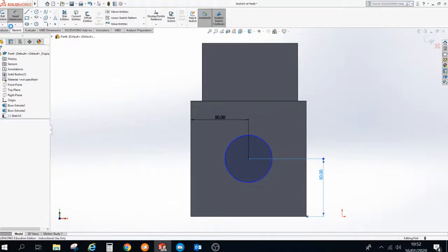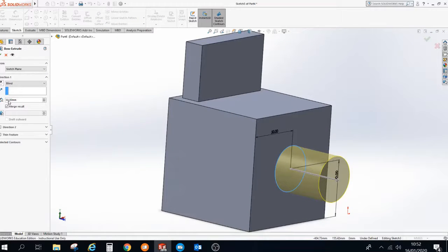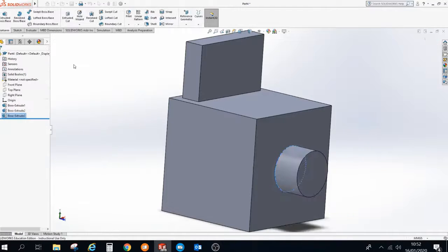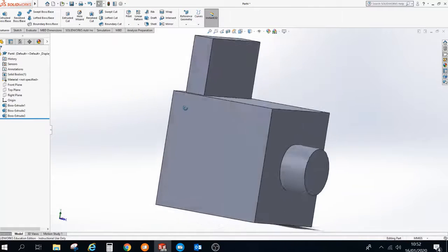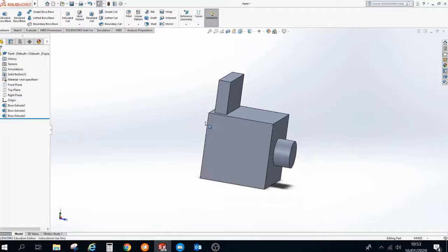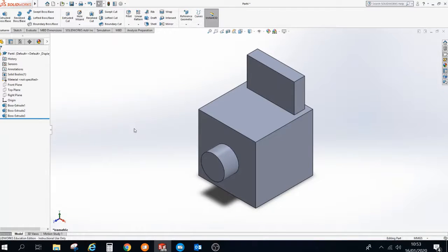Exit my sketch. I've already told it that I want to do an extrusion, so if we just slightly rotate, let's remember that last size of 50, change that down to 25 and confirm. So we'll have a wee spin around to see what I've created now. So here is my object, and Control 7 just to get a nice isometric view of it.